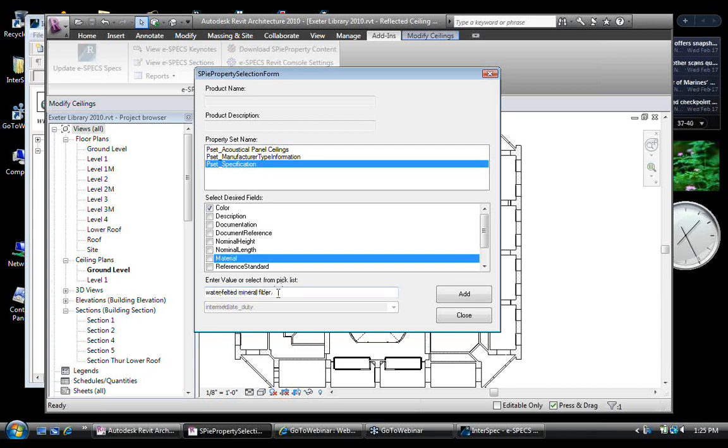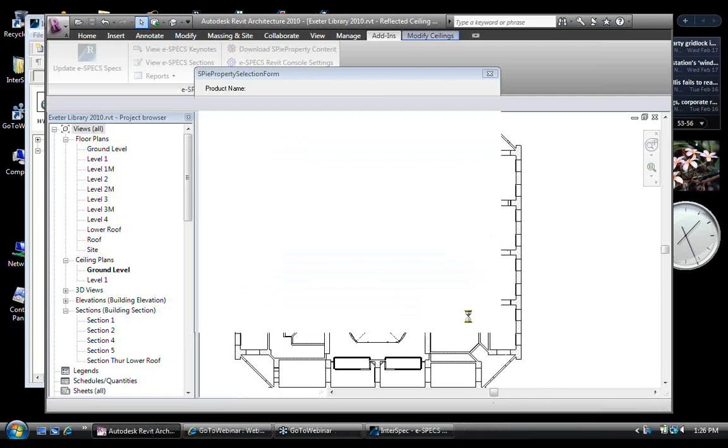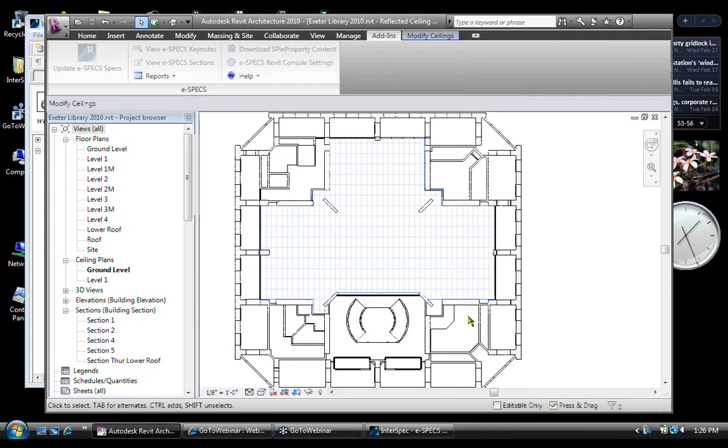These are very important pieces of information, but as a designer, I would never know that. I would have no idea that the Aspen has this type of material in it. So this might be very valuable for me to put into the BIM model because a downstream application may require the material of the panel to do calculations on sound prevention and sound transmission. So this is what we're really getting to here. I go in as a designer and select from this list of non-proprietary information, and I'm going to enter that into the ceiling.